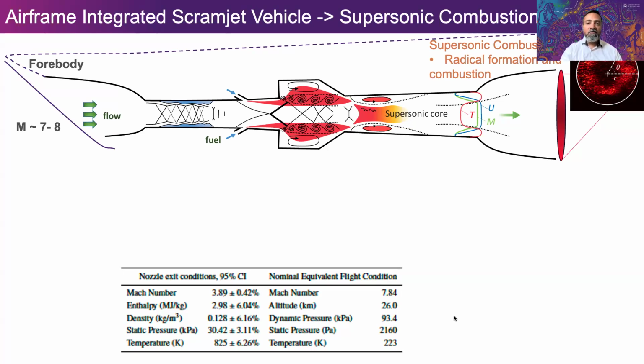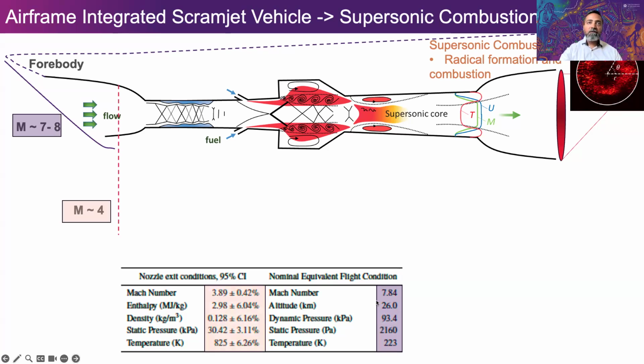Now the next question is, when you're not dealing with a full three-dimensional scramjet, how do you guarantee that you achieve the right conditions in the combustor in terms of the pressure you need with the compression? So we thought about this and we decided that this is what we'll do. We're targeting this condition. That's our flight condition. We can use a Mach 4 nozzle in the facility.